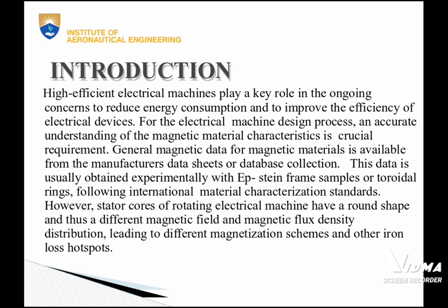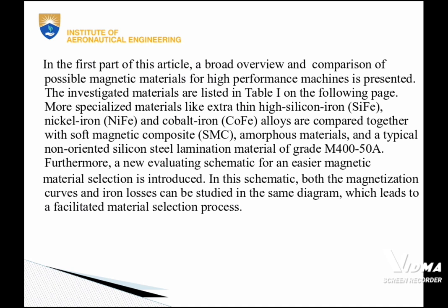However, stator cores of rotating electrical machines have a round shape, and those have a different magnetic field and magnetic flux density distribution, leading to different magnetization schemes and other iron loss hotspots.